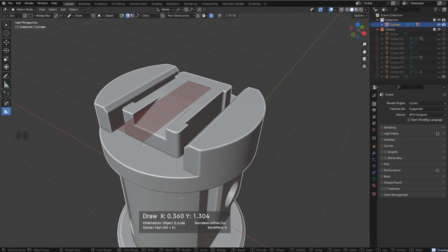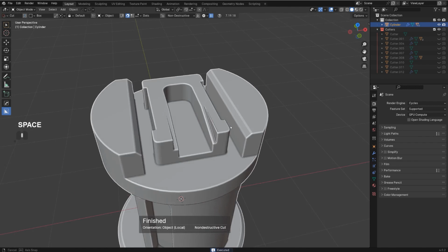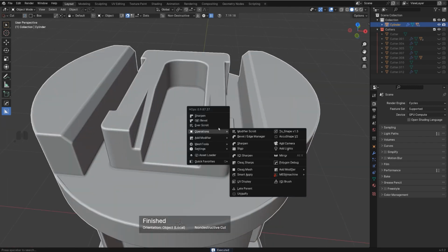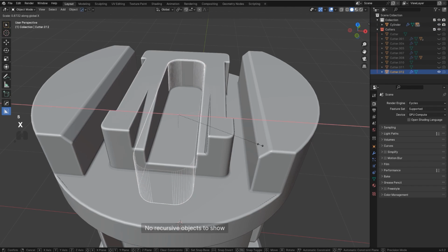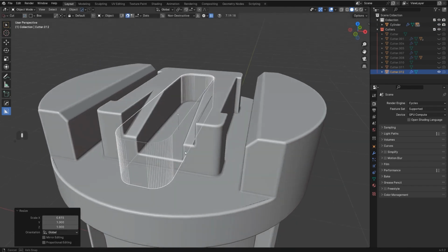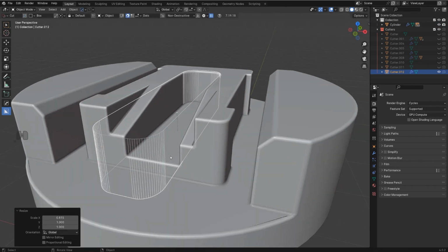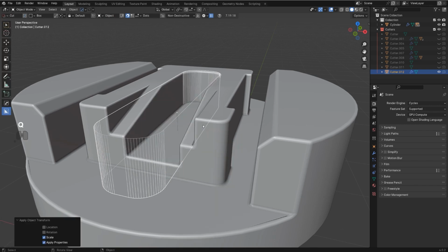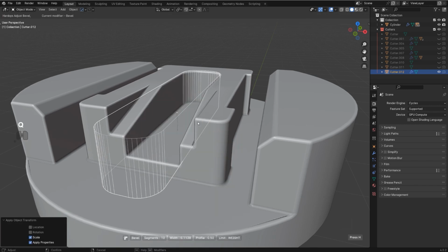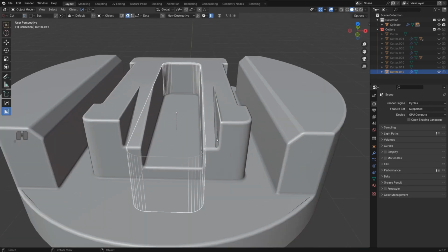In fact, this could be interesting. Hang on. Ooh. That's a little bit too... I need to narrow it down slightly. So SX. When you scale something like this, you need to reapply scale because you will have problems with bevels. So watch this. Apply scale. Boom. See what I mean? Now solidify bevel, and I'm gonna scroll it down because that's insanity. Something like this will do.